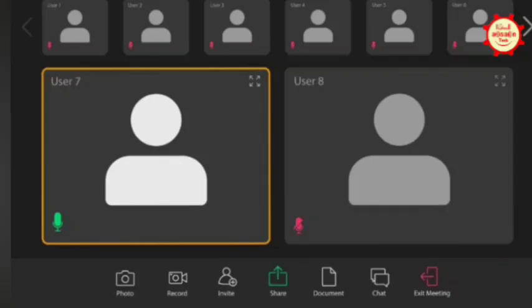Ramakrishna, do you want to tell? Yeah. Actually, what kind of tray it should be will be specified by the licensor, but the actual detailing will be done by the tray vendor. Okay, I know the fabrication vendor of the column normally does the tray support, what is called TSR.